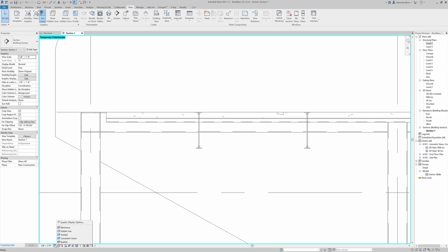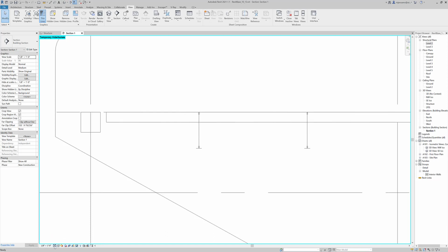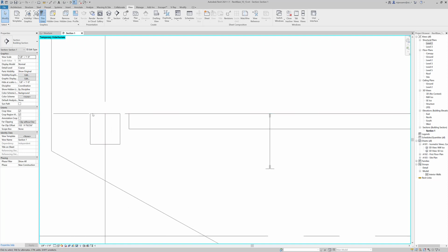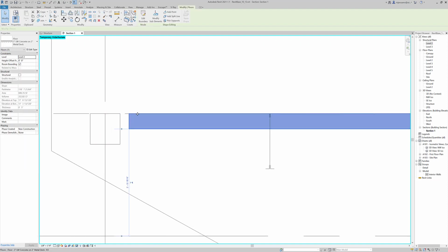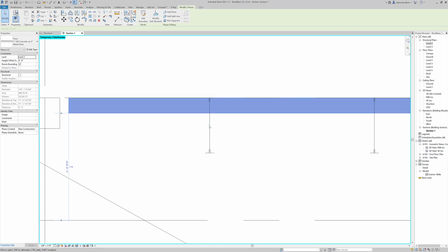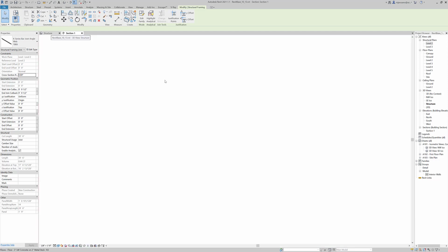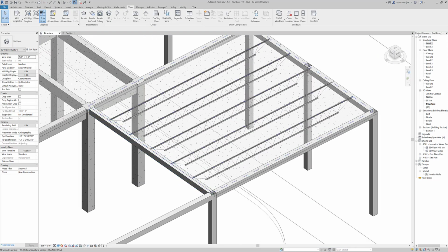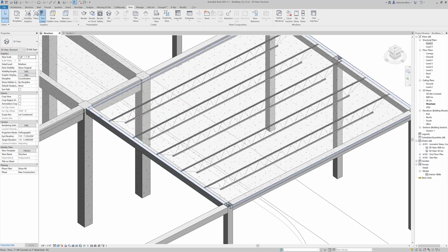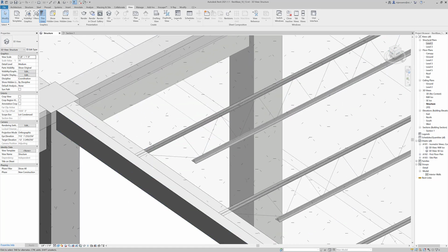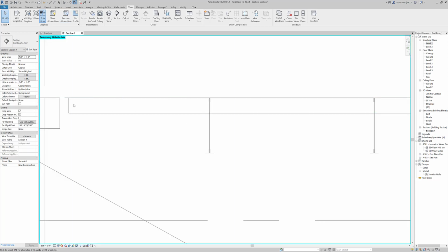Now we're not going to see a ton of difference between, let's say, a medium and a fine, but when we go to coarse, we can understand the diagram of this a little bit better. We have a beam, a hollow beam here. We have a floor which spans 5 inches, and then we have these joists which have a top and a bottom chord. Let's go back to the structure here, and let's see how we can modify these things to be in the right place, because if you look here or if you look in the section, they're all sort of being absorbed.